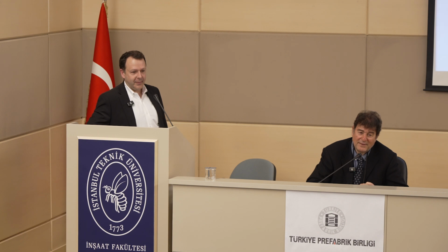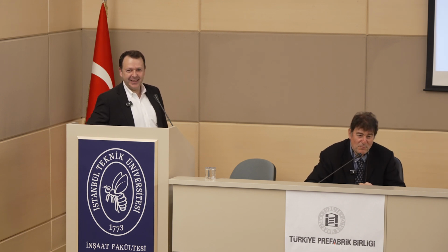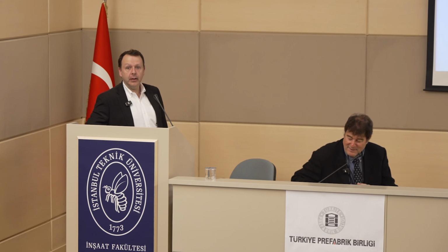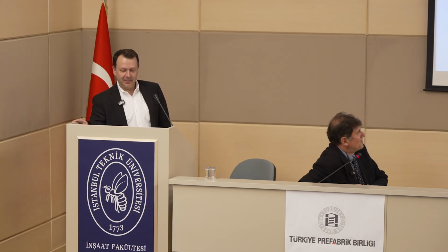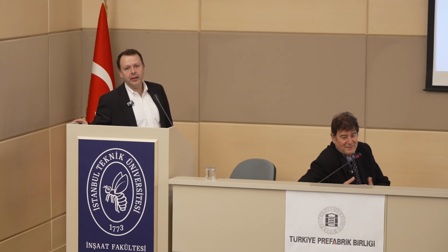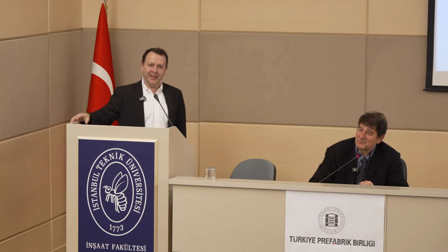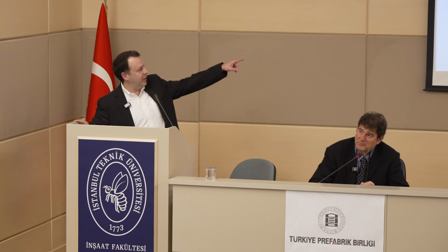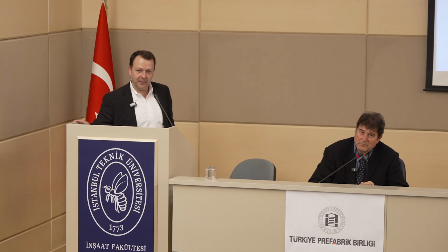Intelligent computer. They took out the hinges at the columns. Any plastic hinge in the column? No plastic hinges. We told the computer not to see hinges in the columns. Yes, you should. In the next step of the model, and in a more detailed model, we would add additional hinges, and you would expect to see a hinge at the base of the column.